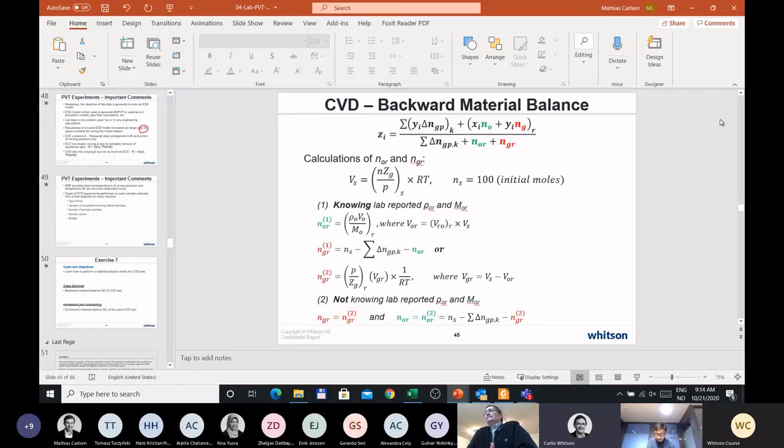Well, I needed DLE data. Okay, well, I don't want to even go to the arguments there, but those 2 pieces of data I think are probably the top of the list. And on compositional data, it's the measurement of the flashed oil density and molecular weight always being provided. If they want to make calculations and adjust those and say we believe in these calculated numbers better, that's fine, but they should at least give us the measured density and molecular weight of the flashed oil in all cases. So I think those are the top 3, if I'm going to make a list.